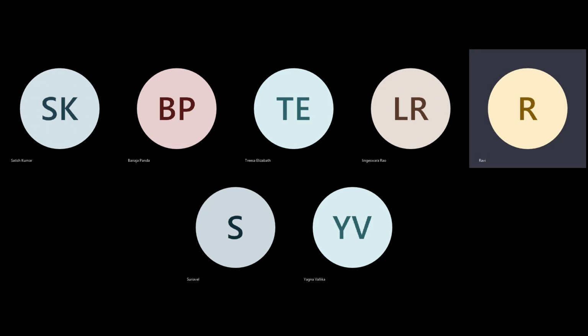No. So 450 nets. And where it is going to be maximum is wherever it is actually exiting the full macro set. Because at the top there may be 20 nets only, but as it comes towards the bottom where it is connecting, more pin nets are actually entering. So that's the peak where it is going to happen. So now 450 nets, and let us say you are talking about vertical layers.